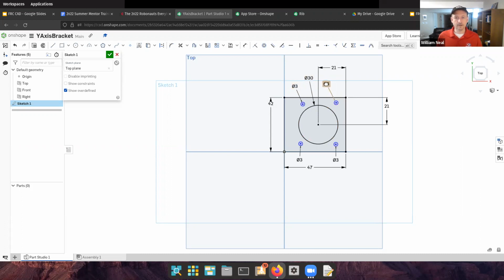So you can play around with how that best looks so that everything is kind of easy to read on the drawing. And there I've got all of the sizes for my hole specified. I'm going to just try specifying distance for all of these. Holding down shift, click these 2, and this distance will be 30 again. And we'll make this side 30. Oops.